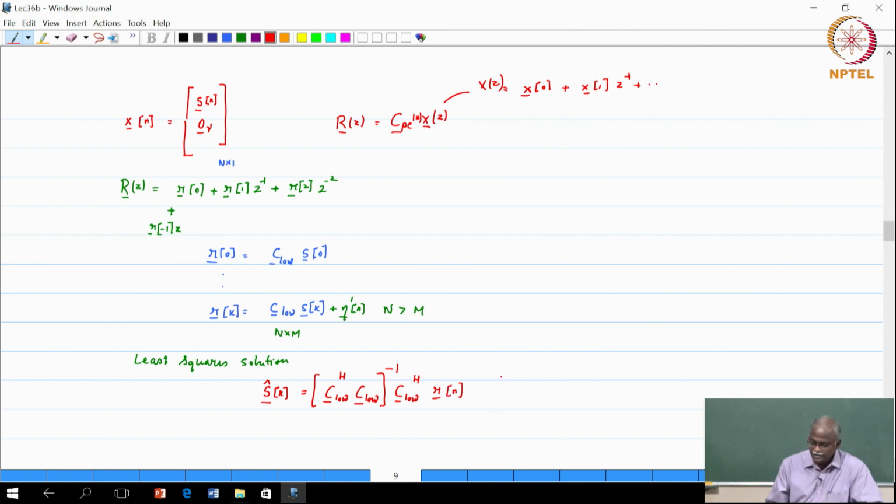Okay. So, this is a block by block decision process, there is no interblock interference, and the way we have gotten rid of the interblock interference is primarily because of the 0 insertion. And maybe what is worth noting here is that C low corresponds to the first m columns of T naught.